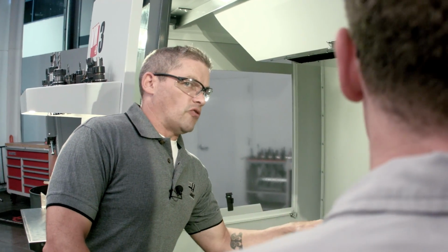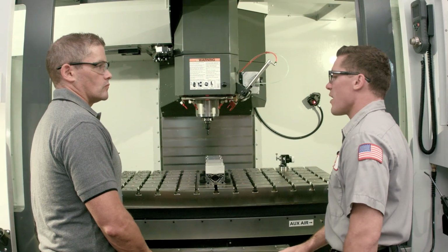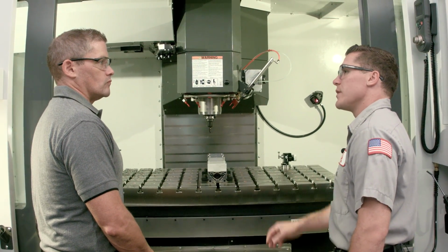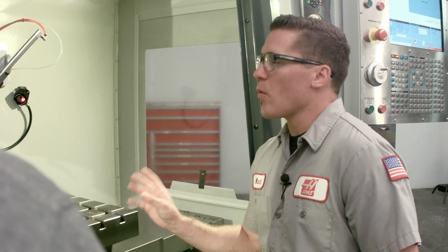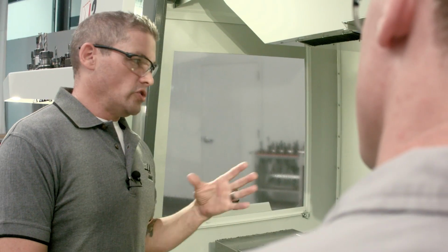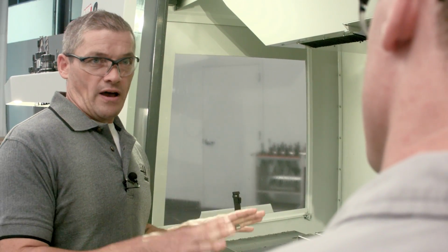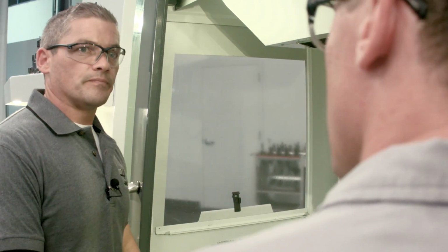How do I know I've got enough oil reaching the tool? Well, most people tend to have the atomizer set to what ends up being too rich of a setting. If you can see oil mist coming out of the nozzle, it's probably set way too high. We're using the oil that comes with the unit, of course. Can you show us what a good baseline atomizer setting is? Yeah, sure.